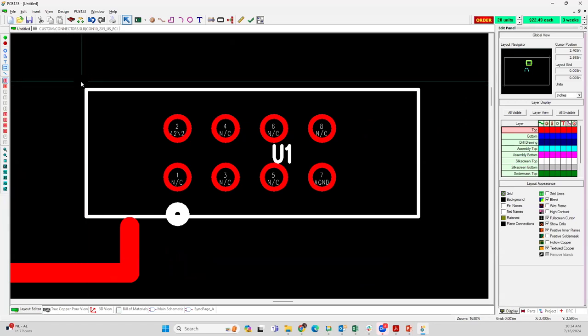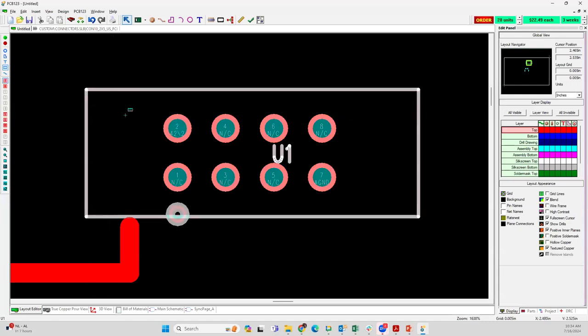You can create that file in a Gerber editor, or if you've got a file in a Gerber editor, just turn off all the other layers and export to DXF your board outline. And if it's a good board outline, it will import correctly into PCB123.